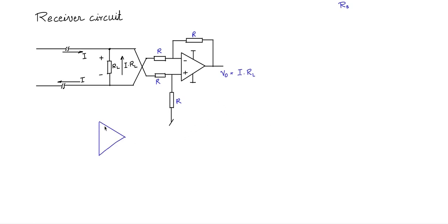Now I will use one more op amp, plus and minus in this fashion, VCC and VEE. And here I will have a potentiometer. This is plus V plus and this is V minus, and tap a point and buffer it. Which means I can adjust the tap here and get from plus V to minus V, any voltage I can get from this tap.